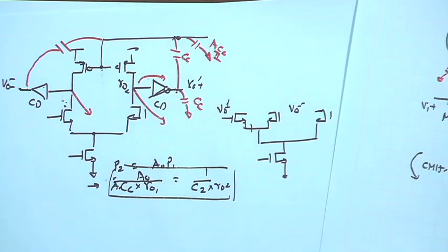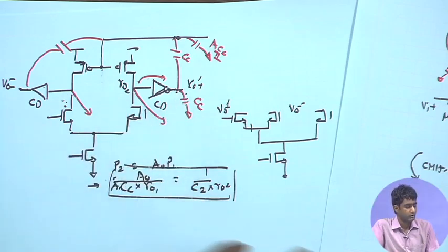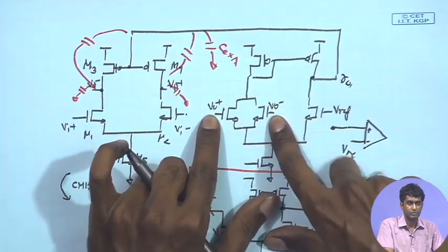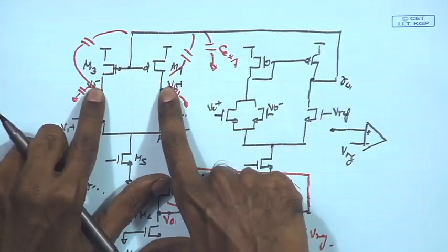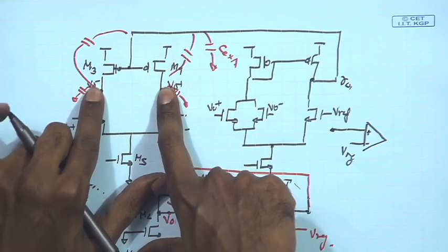Sir, but the DC point and Vref will change in this case. Why? Because of the common drain, the DC bias point will change. You have to make sure that the DC bias point of the common drain stage is sufficient for driving the input over here. So, in general, this DC bias point of the first stage will not be very low, it will be relatively high.